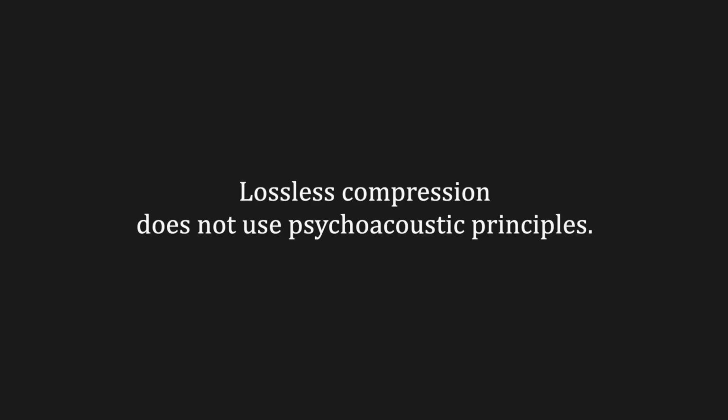The bitrate reduction depends on the input word length, with lower precision signals compressing more efficiently. Each extra input bit adds roughly 1 bit to the compressed output. Unlike lossy coding, lossless compression does not use psychoacoustic principles like masking. This makes development simpler since transparency is guaranteed and subjective listening tests aren't needed. However, timing and jitter still require careful engineering.